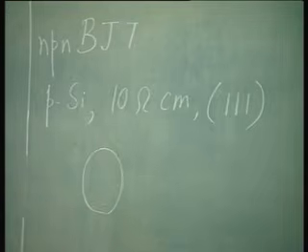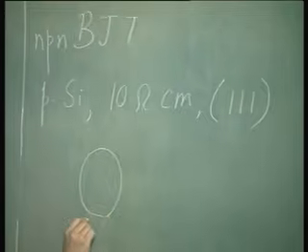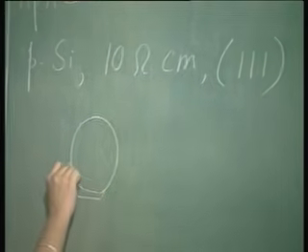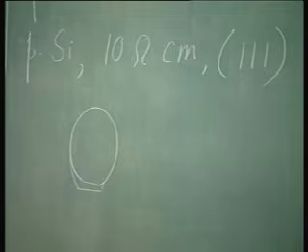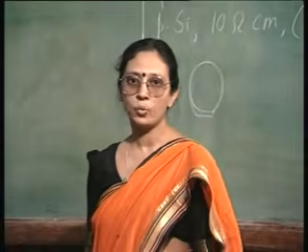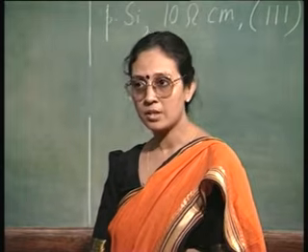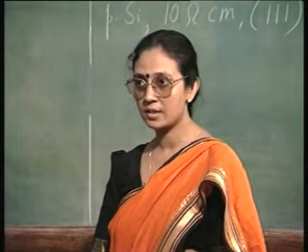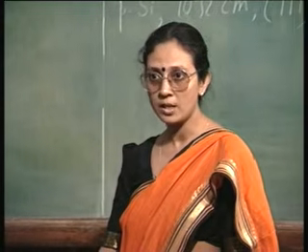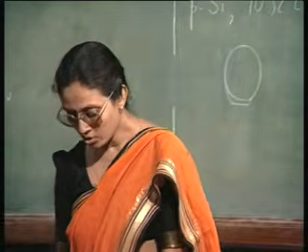This disc has a particular thickness, usually about a few hundred microns thick, maybe about 500 micron thick. The exact thickness will depend on the diameter of the crystal. The bigger the crystal, the thicker it has to be in order to give it mechanical stability. Okay.